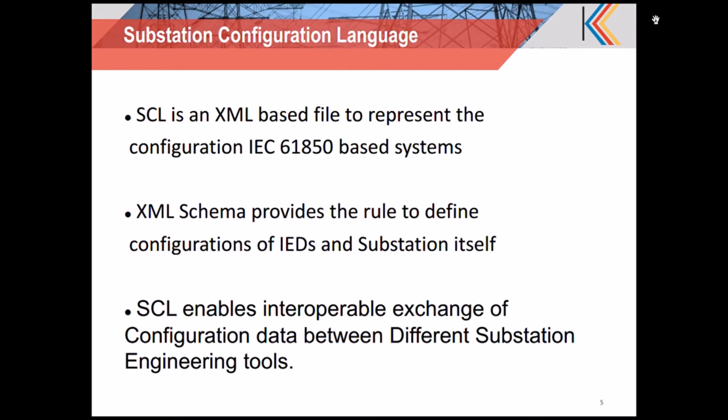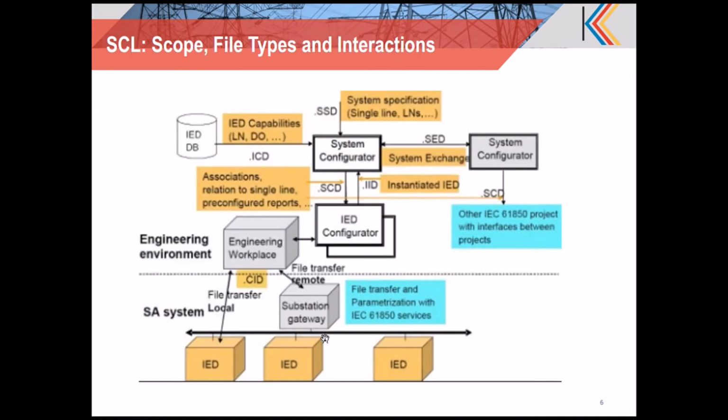A schema is defined for the configuration of IEDs and substations, and this ensures that the complete system is interoperable, with the exchange of configuration data between different substation engineering tools. So this is basically the SCL scope, file types and interactions.